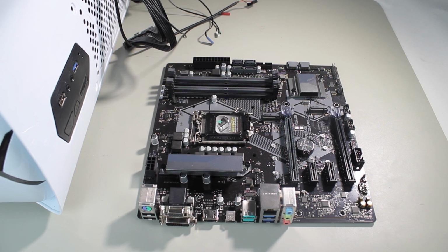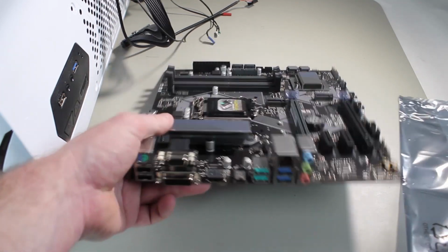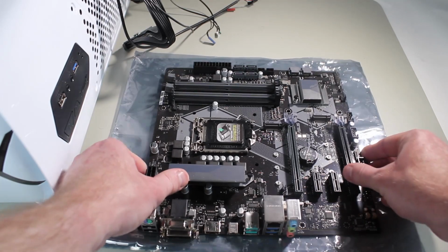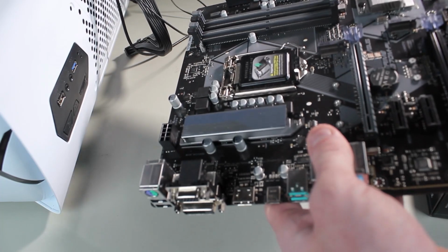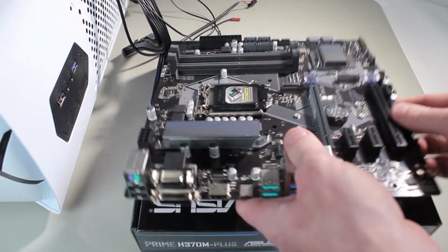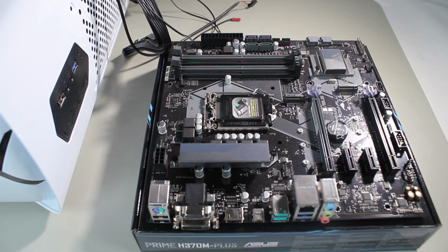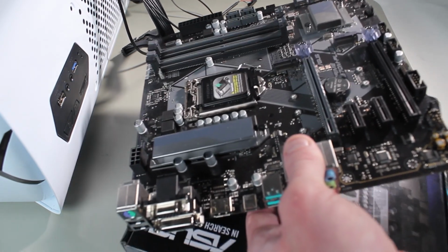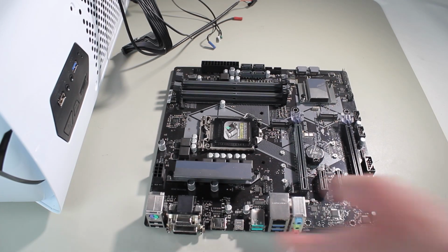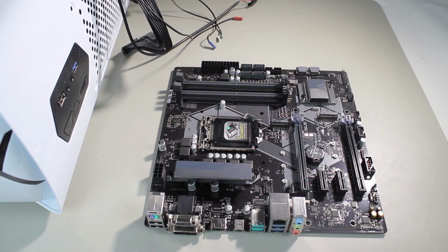In this case, I have the motherboard on an anti-static mat. If this is not available, one option you have is to place the motherboard on the anti-static package that it came in. The next option is to use the cardboard box that the motherboard came in. Either solution will prevent static electricity getting to the motherboard. Also, if you are working on a hard surface, the box will help prevent damage to the bottom of the motherboard. In this case, I will leave the motherboard on the anti-static mat since it gives me anti-static protection and, as the mat is quite soft, it will not damage the motherboard.